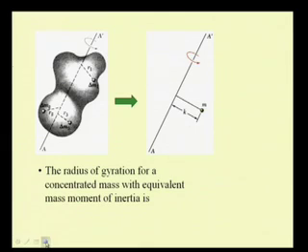So, that is how we define the radius of gyration, and the second moment of this mass with respect to this axis is k square m, which should be equal to the second moment of the mass of this entire rigid body with respect to this axis A prime, which is say I. Then I is equal to k square m, and from this we can find the radius of gyration k as root of I by m.